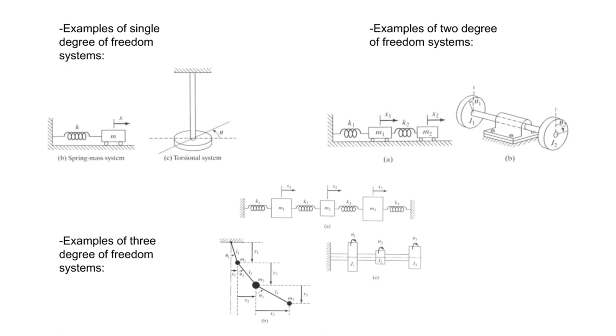In the B diagram, the torsional system, 2 rotors are on the shaft, one on each side, and these 2 rotors are twisted, one clockwise and the other anti-clockwise, by angles theta 1 and theta 2. Therefore, to describe that system, 2 angular displacements are required, theta 1 and theta 2. The equation of motion will be based on these theta 1 and theta 2 for this system.